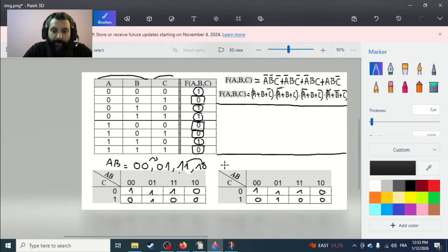Okay, we practically finished, but not yet. The last thing: you have to be sure that the last one respects the same rule with the first one. We are creating a circular order. Passing from the last one to the first one, only one variable should change. In this case, it's the value of A. A for the last value is 1, it becomes 0. This is a condition to use the Karnaugh Map.